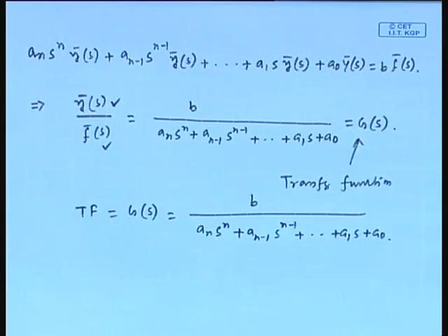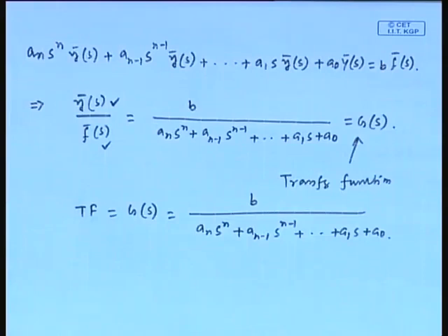Fine. So, this transfer function basically represents the linear or linearized input output model in terms of deviation variables. You see, this is the input output model. Fine. So, transfer function represents the linear or linearized input output model in S domain, Laplace domain.